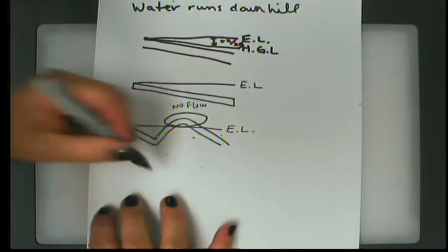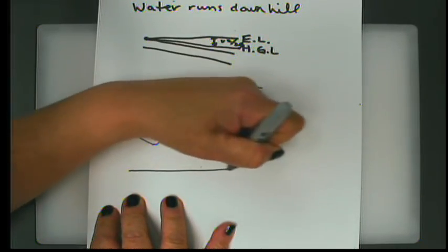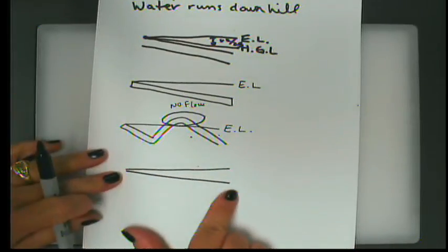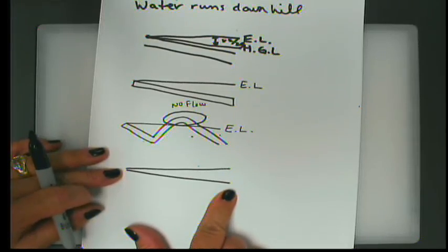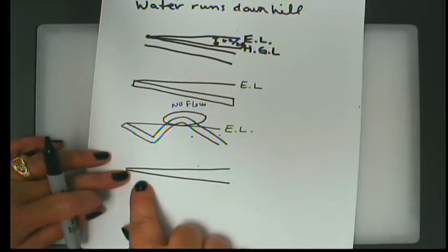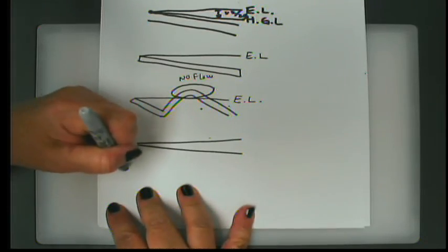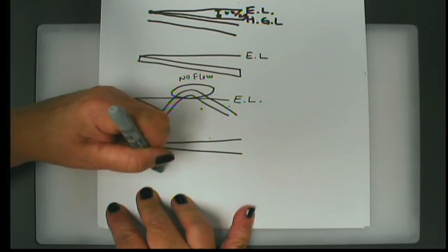So although we talk about the energy line being constant, the energy line actually goes down in elevation based on the line losses, on the roughness of the pipe and the size of the pipe. And all those things are generally available to you in modeling or simulation software, which we'll talk about farther on down the line. So section 3.8 talks about restrictions on the Bernoulli equation.